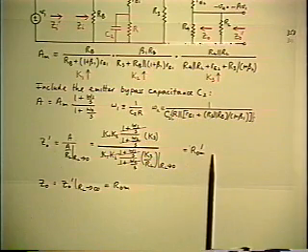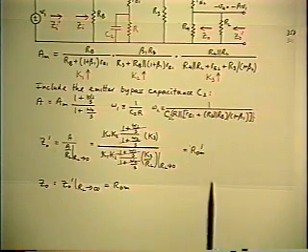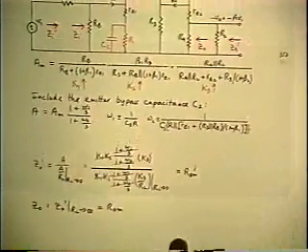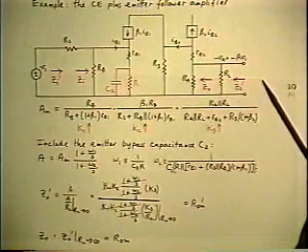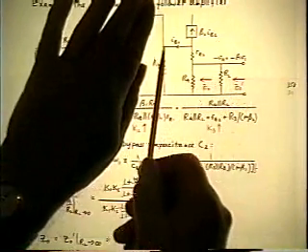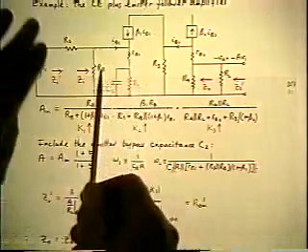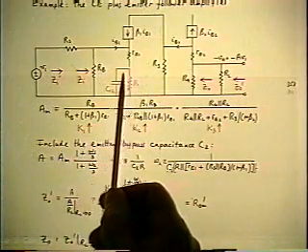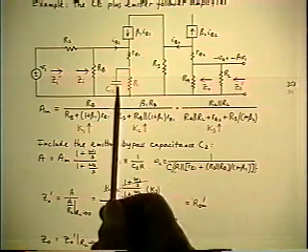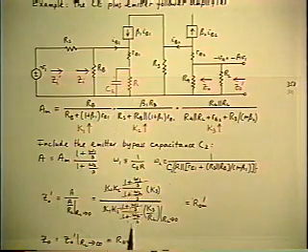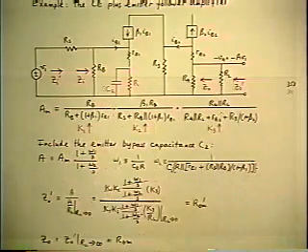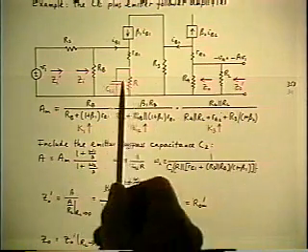There is no frequency responsive output impedance, which again in this particular simple example of course is really obvious, because when you look back in from the output, impedance is contributed by elements back to R3, and what happens before that doesn't get into the game anyway. So it makes no difference whether the C2 is there or not. The cancellation of the corresponding factor is the way that shows up in the output. The C2 has no effect.